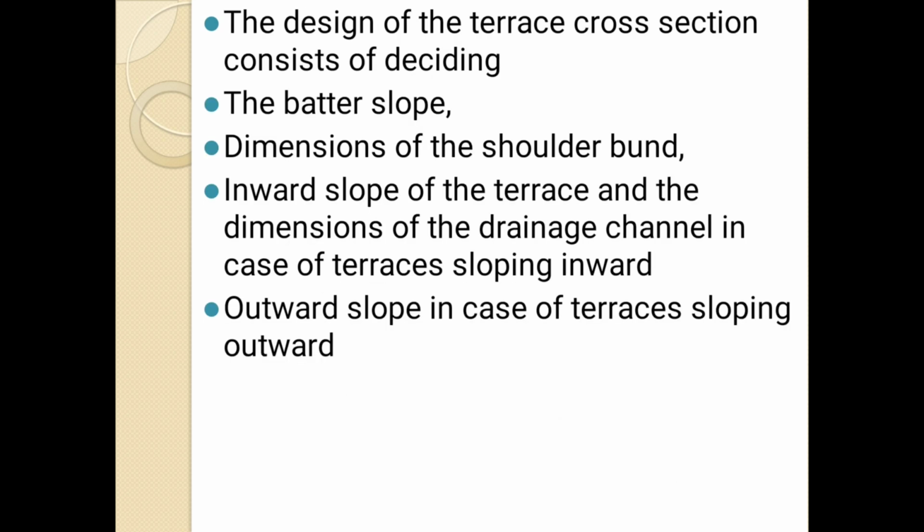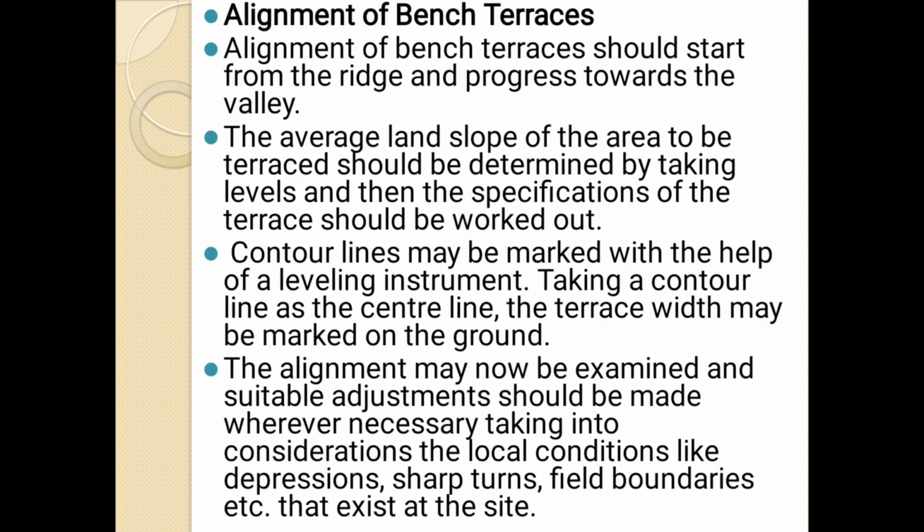A design of terrace cross section consists of the batter slope, the dimension of the shoulder bend, the inward slope of the terrace, and the dimension of the drainage channel in case of terrace sloping inward. For the outward case, the terrace is sloping in the outward direction.